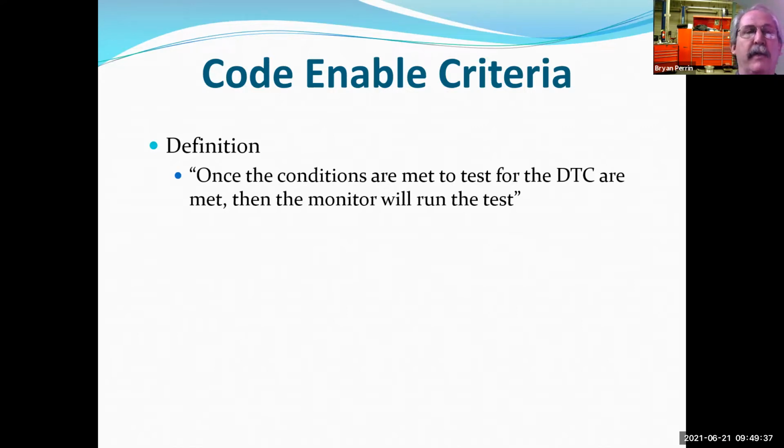So for example, I mentioned misfire. Misfire breaks the engine revolutions into blocks of 200 revolutions, or 200 cycles actually. I think is it revolution or cycles? Maybe it is revolutions. But blocks of 200. And what we're looking at is, did you misfire too many times within that 200? Or when I put 5 of these together at 1,000, did you misfire too many times within that 1,000?